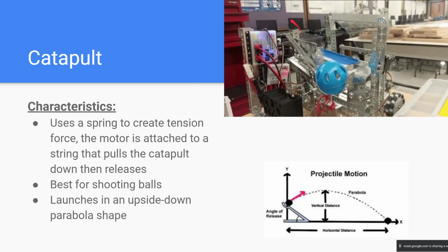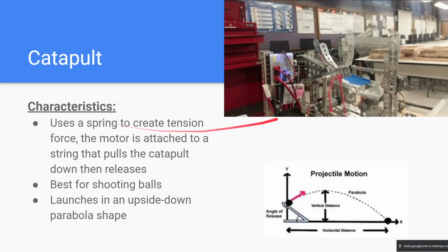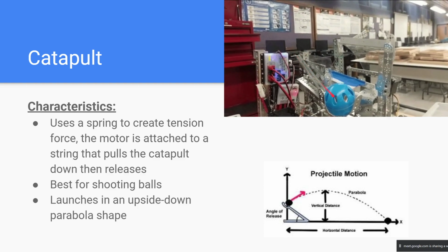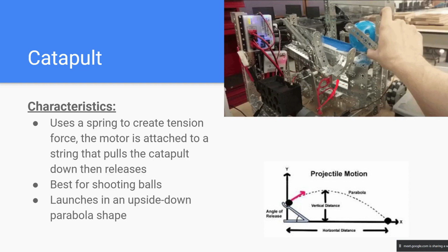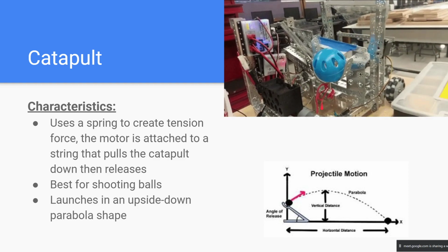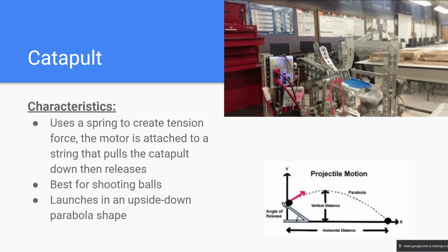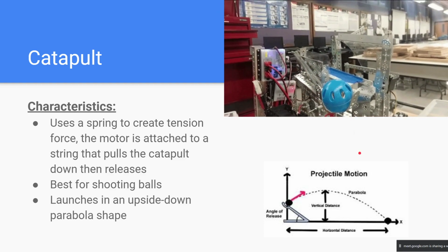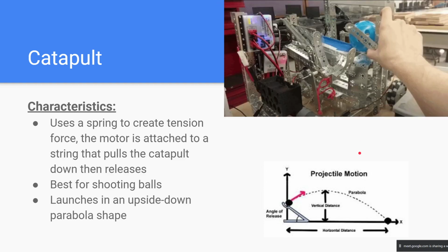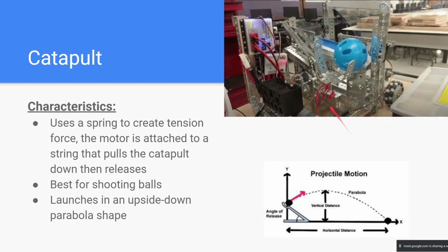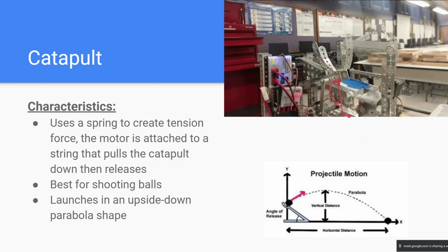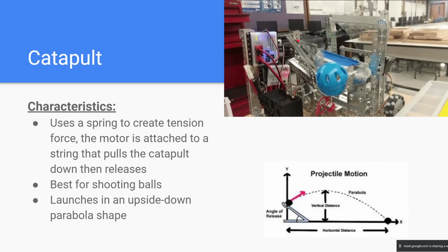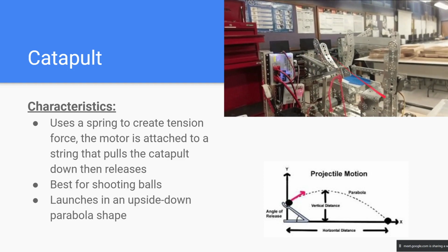It takes up almost this whole robot. So the way it works is that this is a spring, and it's creating tension, and then there's also a rope, and there's a motor somewhere below. The motor is just spinning the rope to bring this channel backwards, and then the motor releases it, so it turns the other way to release, and then the spring is really doing all the work here. It just pops it back forward. Yeah. That's just how it works.